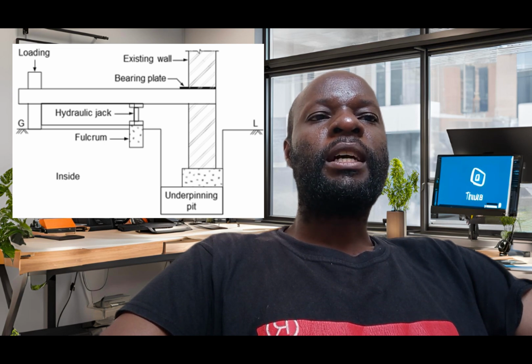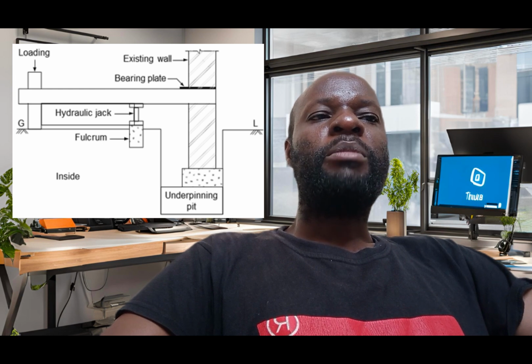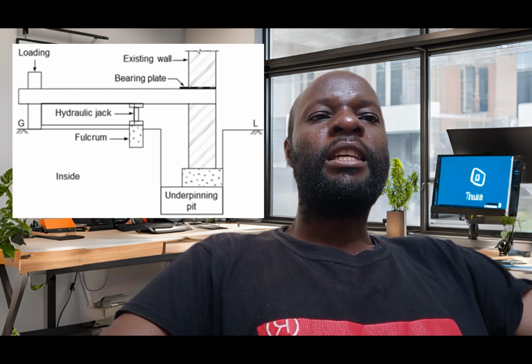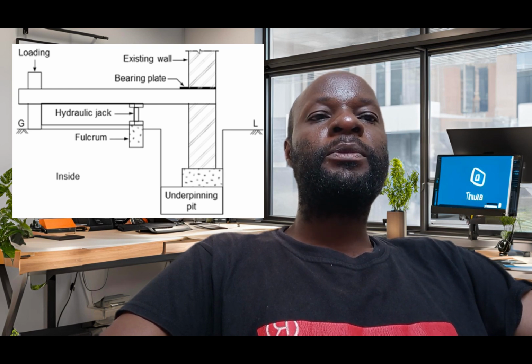And then we have the pit underpinning method. The pit technique of underpinning is often performed by methodically digging the area in phases. After that, needles that have bearing panels attached to them are placed through all of these perforations and stabilized by jacks. After this, excavation will begin, first to a depth equal to the level of the existing foundation, and later to the desired depth. That is what we mean by pit underpinning method.